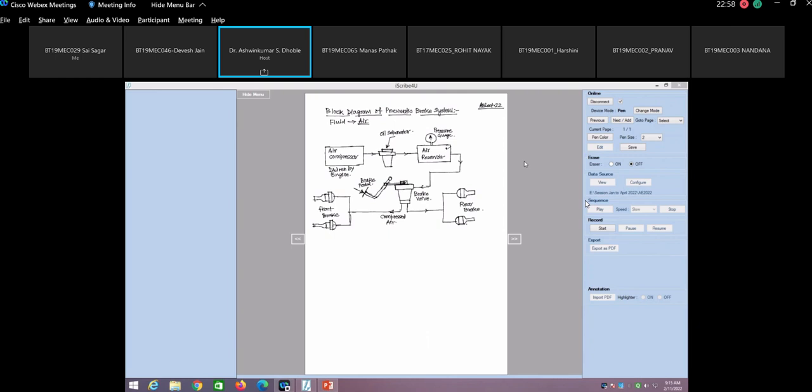So in that process, the oil traces may come along with the air, and you require to separate that, otherwise it will go into the system, and it may have a corrosive effect on the valve, it may have a corrosive effect on the cylinders which are used for actuation of the brakes at the front and rear. Okay, that is basically the oil separator.